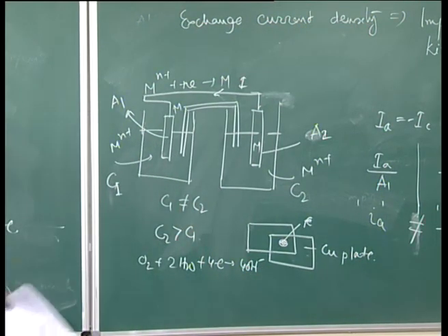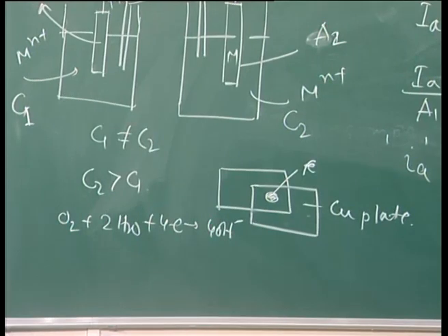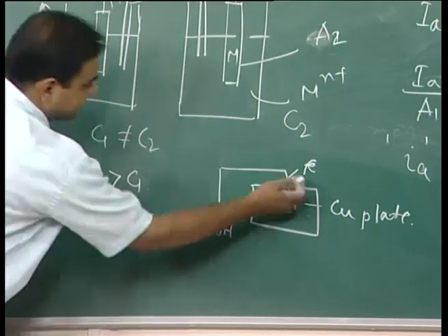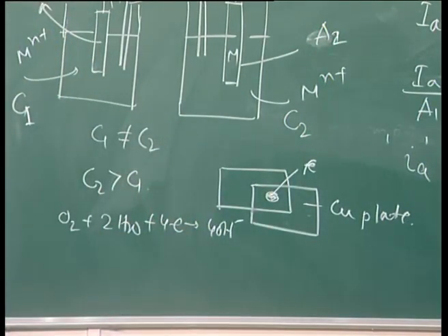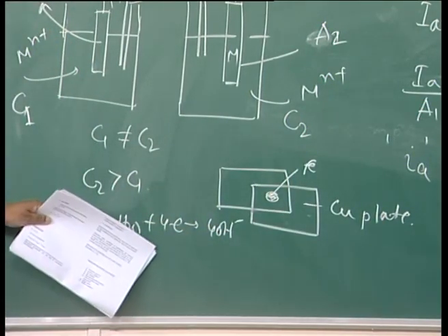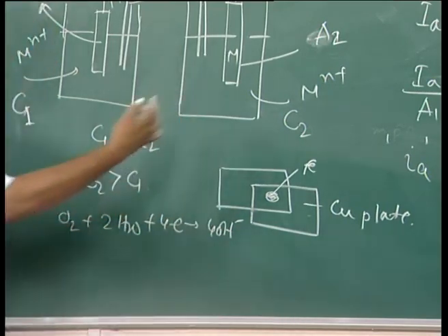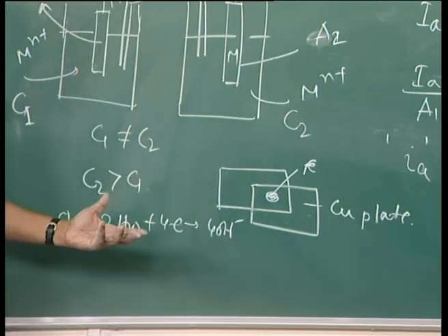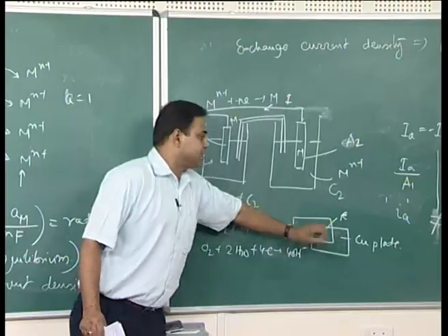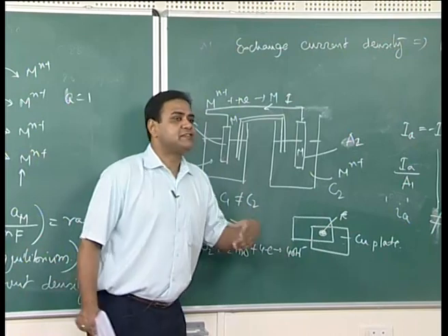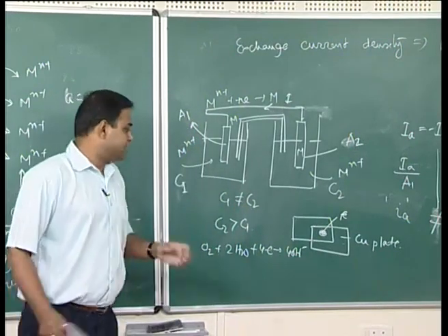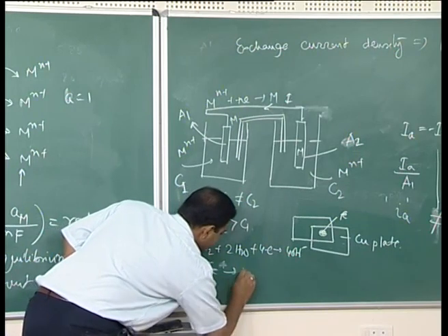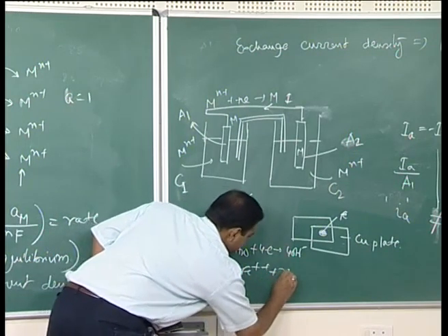This is the cathodic reaction in a neutral solution, since seawater is neutral. If you compare the area ratio of the cathodic and anodic sections, the iron is acting as the anodic area, and the anodic reaction is Fe going to Fe2+ + 2e-.